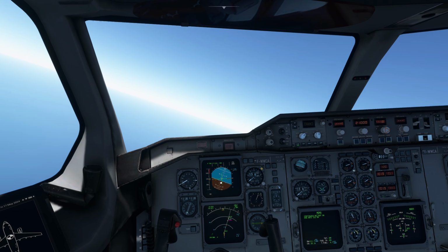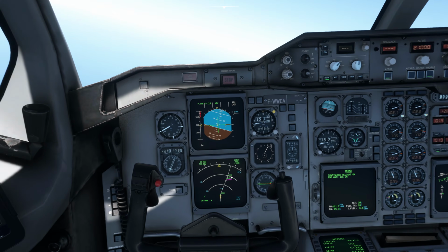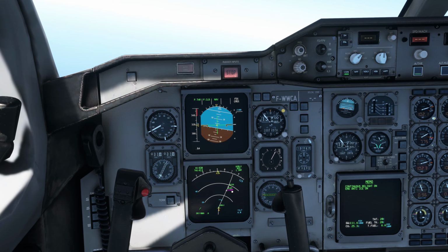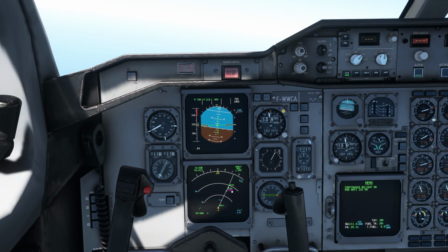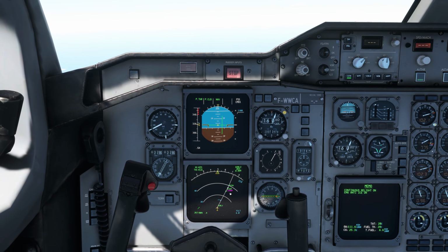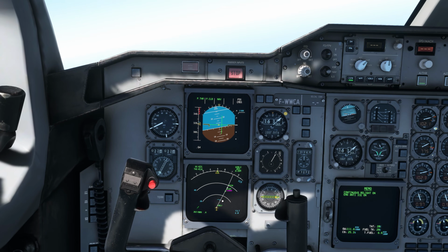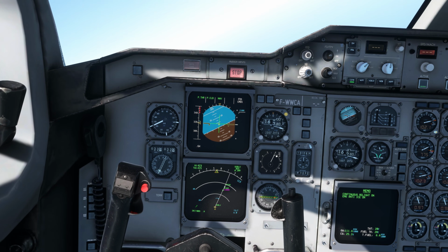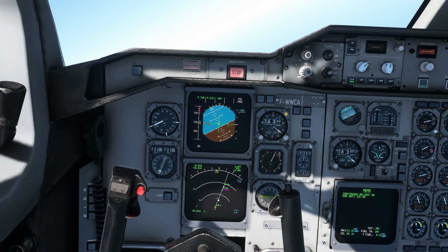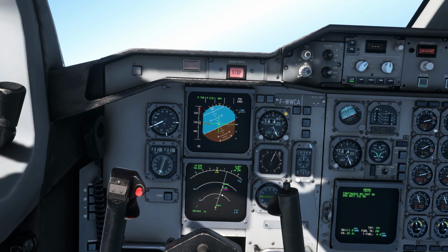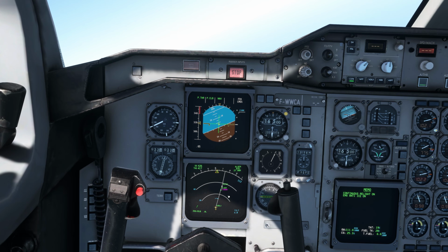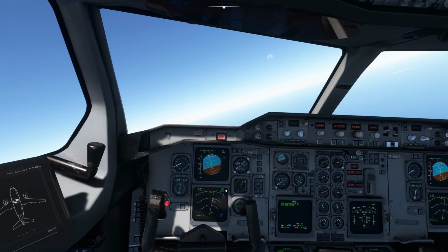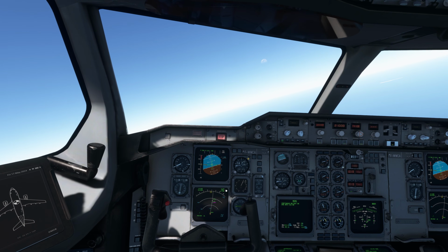Okay. So on your screen you can see the navigation display, 21,000 below. By this point the plane will be or should be at 21,000 feet or below, and you can see this arrow coming, which is giving me an indication that by this point, at this given rate of climb, the plane will be at 21,000 feet. And as soon as I cross this point, I will again start to climb to 28,000 feet, which is my designated altitude for this flight.